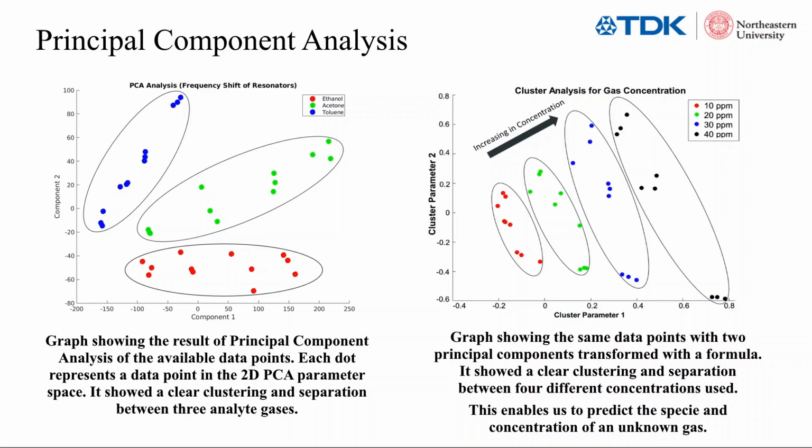In summary, we have demonstrated a micromachined quartz-based gas sensing platform with a quick response time and the ability to determine the species and concentration of an unknown aniline gas using principal component analysis.